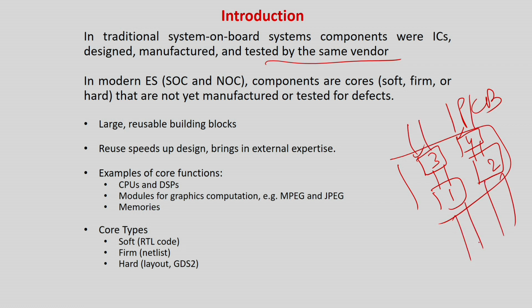But still you can make a probe here. It is simpler to probe these lines and look at the values. That is possible. But it's slightly difficult, not as simple as the standard IOs, but still you can do it as a board. But in a die, if you think silicon, you cannot probe this. You require an external prober, and it's very difficult to break the chip and actually probe these lines. In a PCB, it is much simpler.